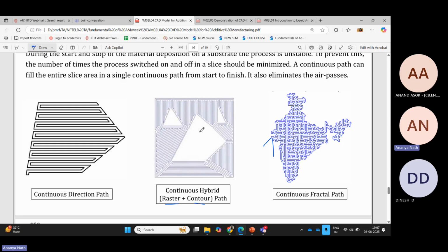But in some cases, it's very common in case of metal or plastic 3D printing both that people don't print with 100% density. Your part should have a 100% density in terms of your layers. Like your layers should not have any porosity. Your layers should not have any high surface roughness. But if you still want to reduce the weight of the part, you can do the topology optimization.